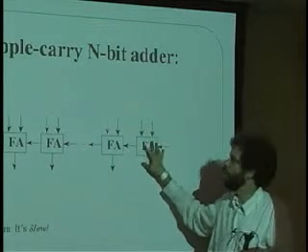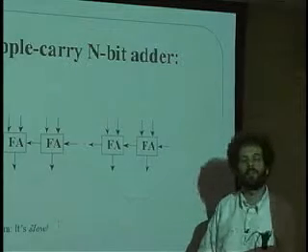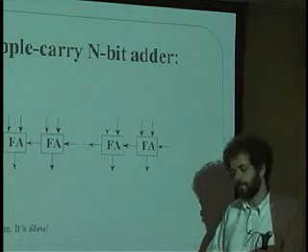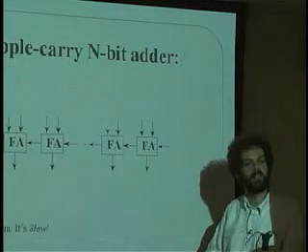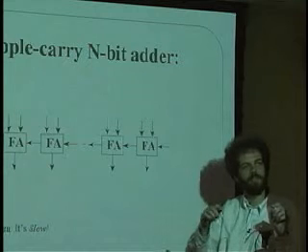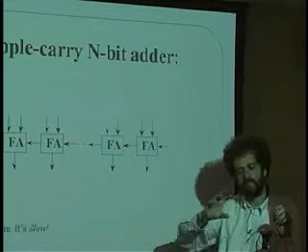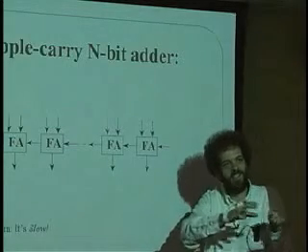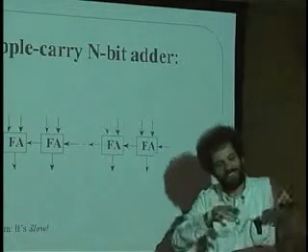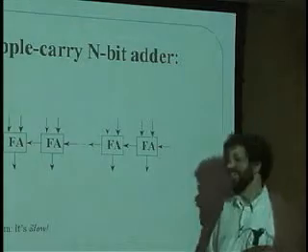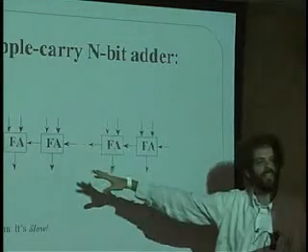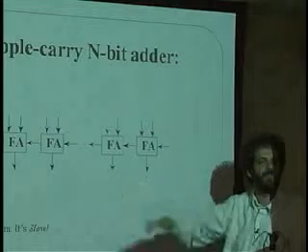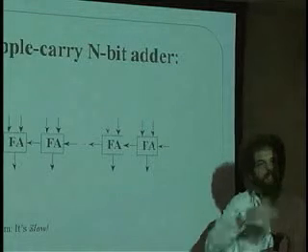But if the carries are required to go all the way through, it's like having an odometer on a car, and it says all nines, right? And you go over that last mile, right? And that last one turns the next 9, and that 9 turns the next 9, and it never quite goes all the way to 0 because it's a little bit skewed. That's kind of how this full adder system works, the ripple chain, but it takes a long time for it to carry over.